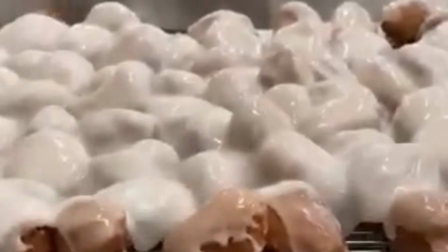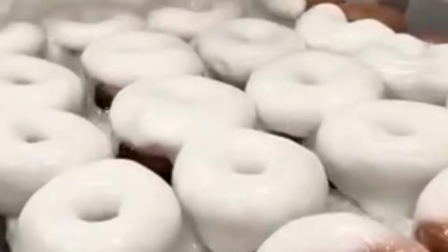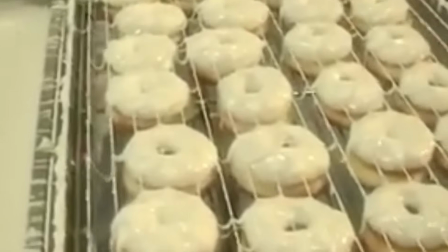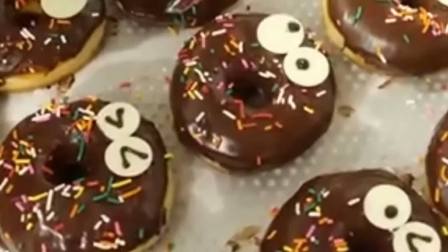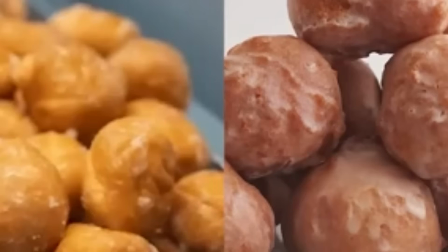Cut dough shapes are placed onto paper-lined proofing trays by a pick-and-place arm. Trays are loaded onto racks that feed into a secondary proofer tunnel. This tunnel maintains consistent humidity and temperature for final rise. Final proofing continues until dough height reaches preset targets. Proofed rings are then transferred onto a mesh belt conveyor leading into the frying system.